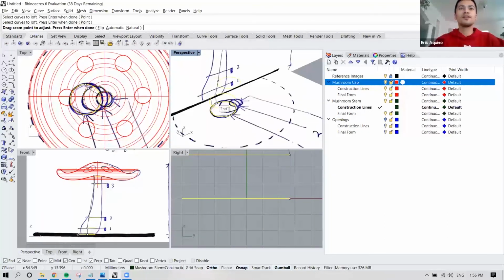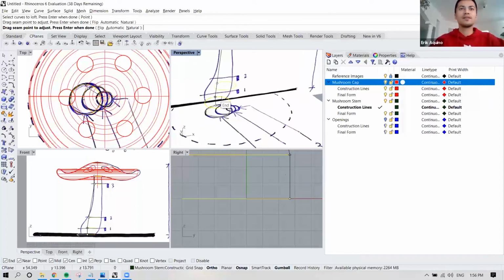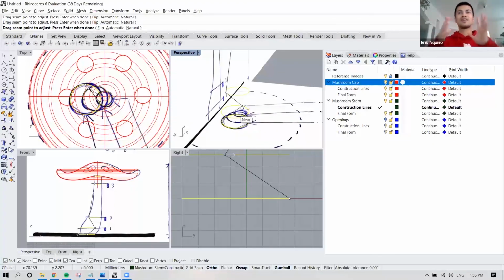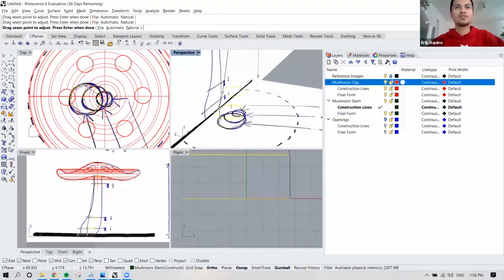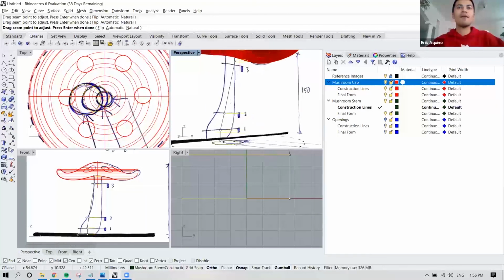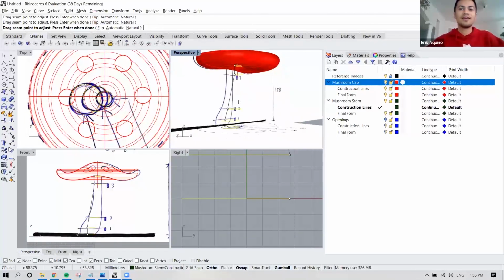But if, for example, your adjustment curve was something like this, then you'll get something a little wonky or funky, and we'll want to have them as aligned as possible. So you can select one of these control points and move them around the curve, and then click again to establish its location. So right now I'm fine with this, and I could hit enter to execute the loft.